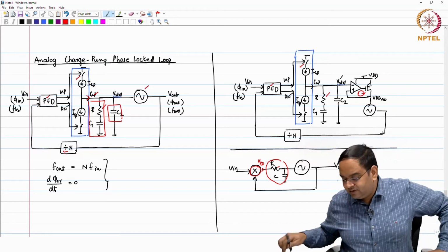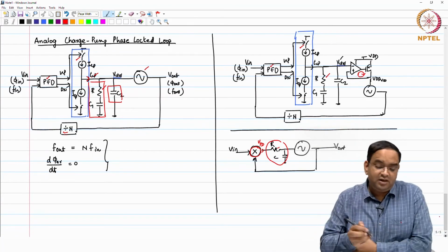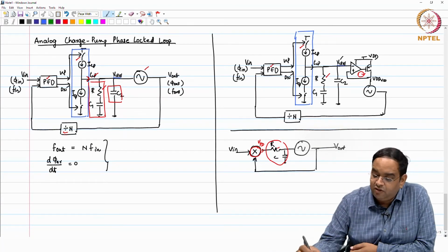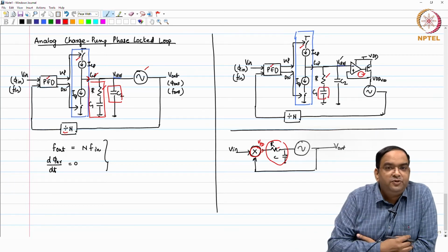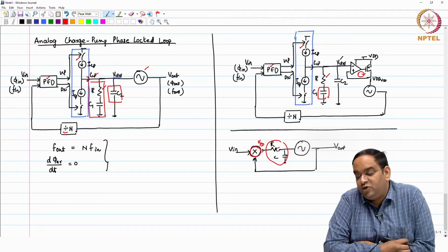After doing all this, we actually went ahead and found the problem with this kind of PLL, that this capacitor takes a lot of area. So, if this capacitor takes a lot of area, can we replace this capacitor using a MOSFET which has a higher density? Well, that led to leakage issues. We could not do that.